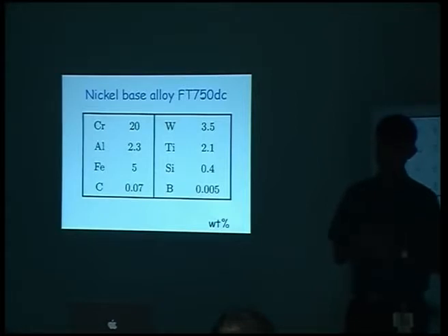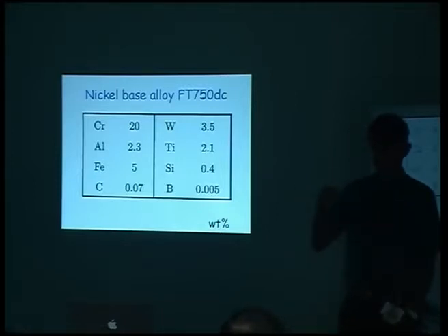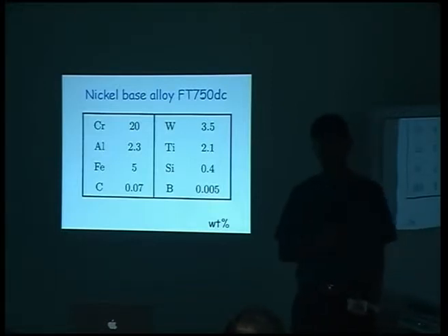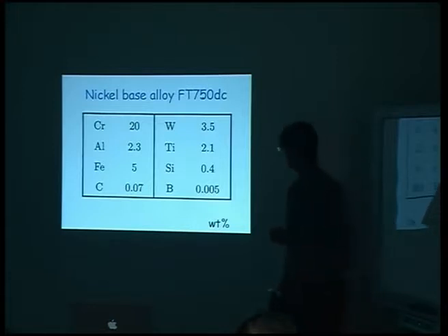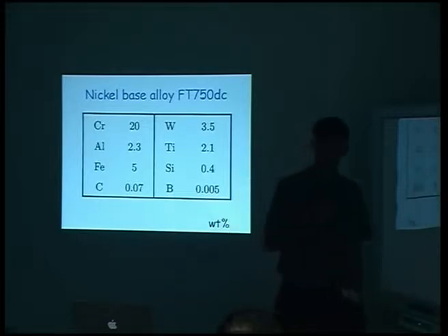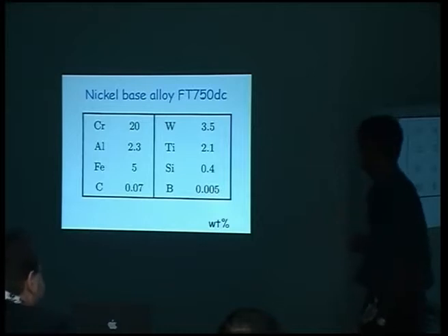And we can do it, because there are a number of technologies which will help to do that. One is to increase the steam temperature. And strangely enough, Denmark is the country which leads in increasing steam temperatures, because they have green laws which say that you must have this much efficiency in power generation. So, unfortunately, ferritic steels will not be able to go to 700 degrees centigrade. Probably not. Never say never, but probably not.